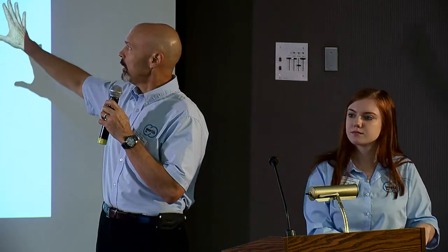You have a CCD chip, and within that CCD chip you have pixels, and those pixels might be 50 micron pixel size, a native resolution of 50 micron. So how do you get down to 2 micron? How can you say you can measure to 2 micron if your pixel size is 50 micron? Because you're going to create an image stack or a voxel.